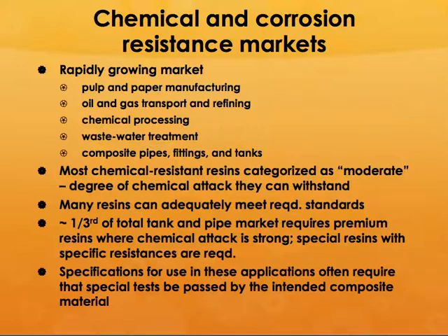Many of the resins can reasonably withstand the different kinds of solvents, but some of them do not. Depending upon the application, suppose the fluid that you are going to be transporting is extremely reactive, then you have to use very high cost and premium resins.